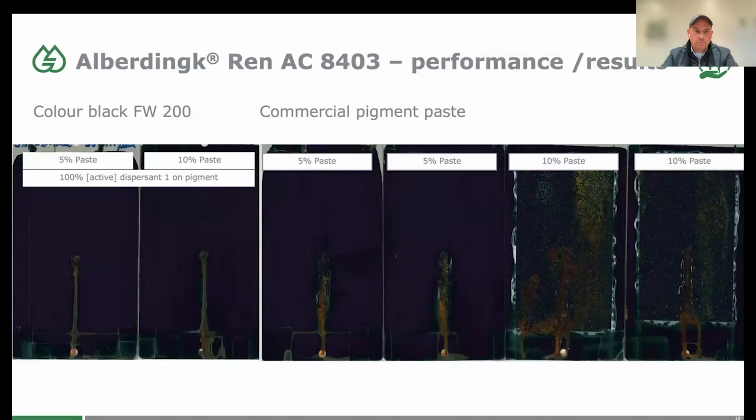So if you want to have a most perfect film, in any case, you're always well advised to prevent adding multivalent cations or acidic or extreme alkaline materials as well in some cases. And you can see here that the most difficult carbon black produces a fantastic corrosion protection after 1,400 hours.